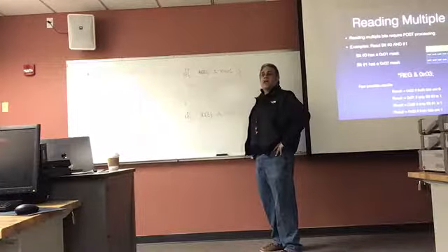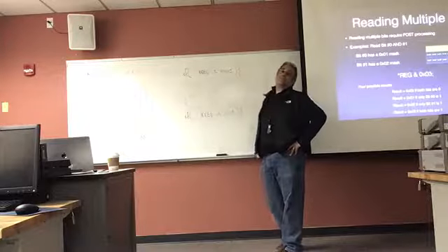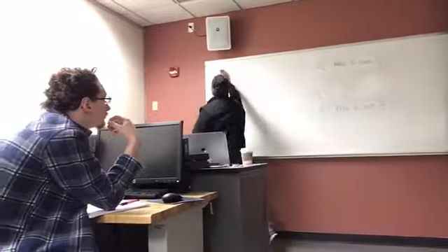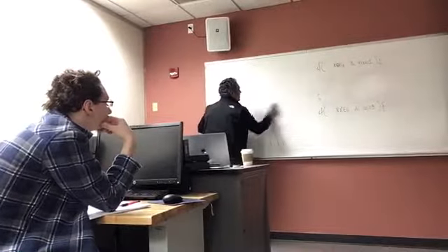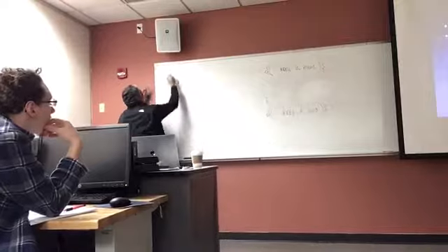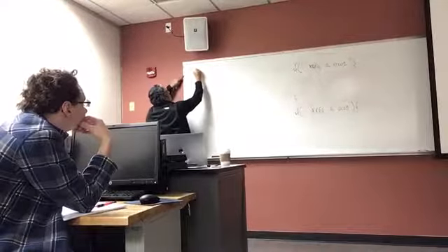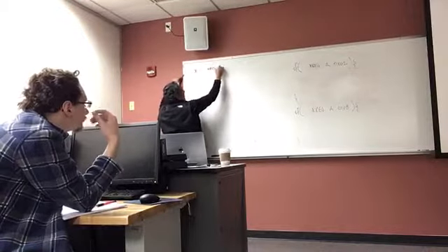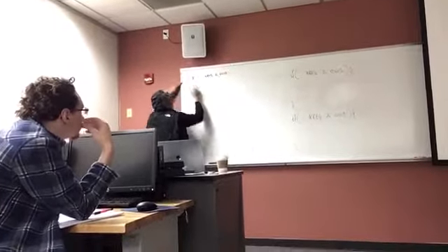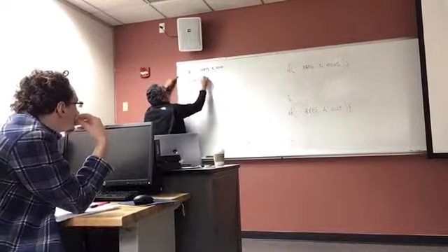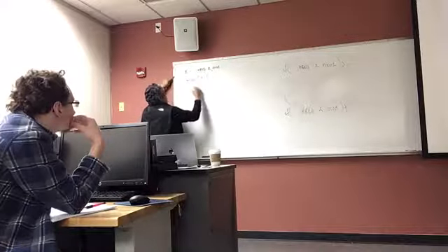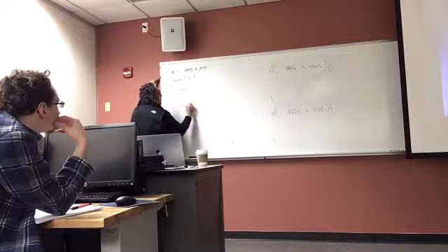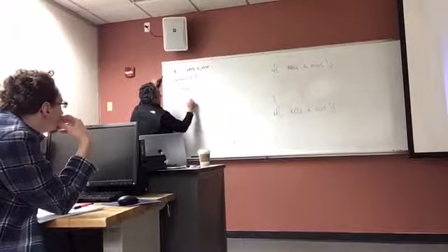Yes and no, I would say. I think most of the time what you tend to see is that people use a switch case for this. And so what they do is something like this. They take a variable and make it equal to your register and hex 3, and then you take a switch and you hit it with an X, and then you go case when it is 0, you have case when it is 1, and of course you have your break here.